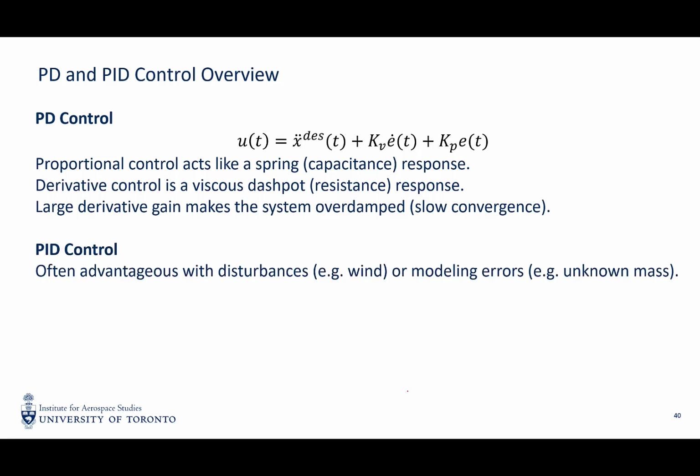Then what about PID? The purpose of adding the integral term is that quite often we have persistent disturbances, such as wind or persistent parameter uncertainties.